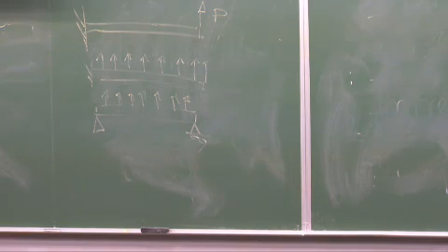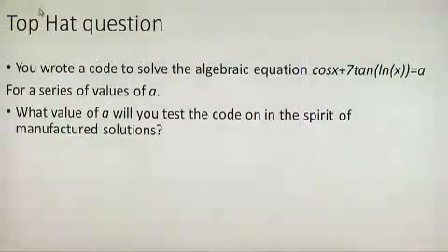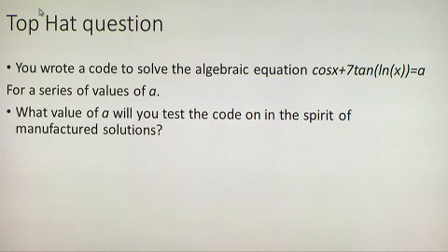So the spirit of manufactured solution is to avoid the heavy work. Applying the right-hand side of the boundary condition and getting a solution is a lot of work. Inventing a solution and finding what loads or sources you need to apply is much easier.